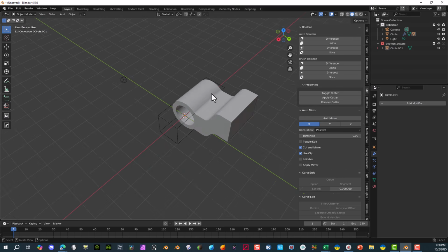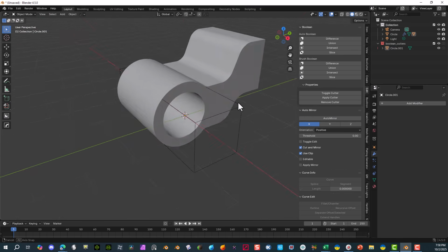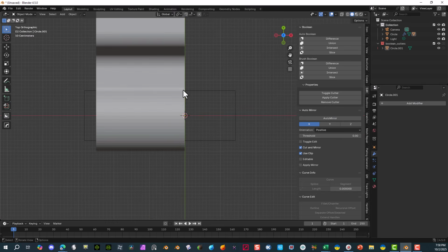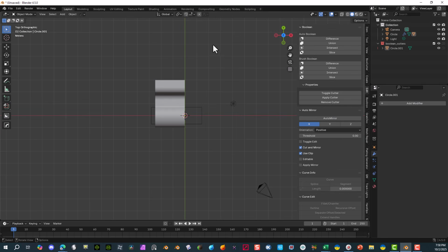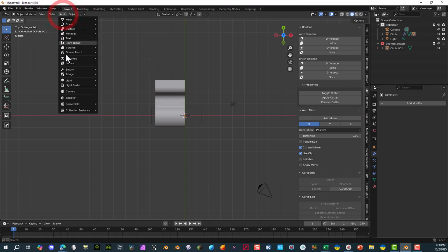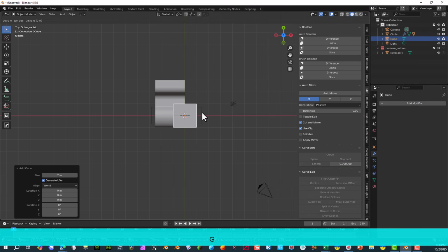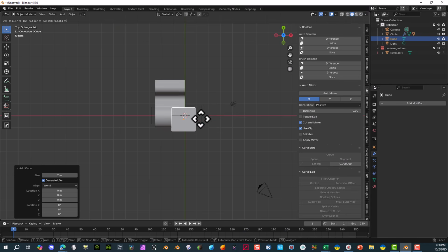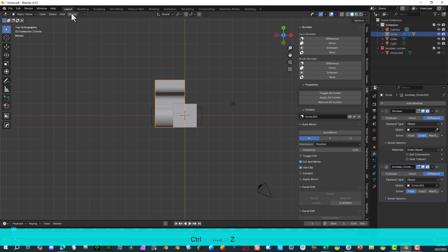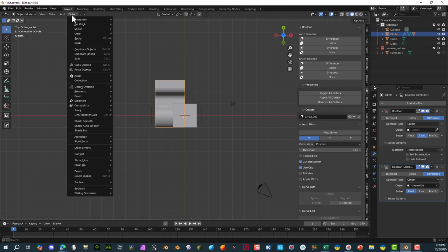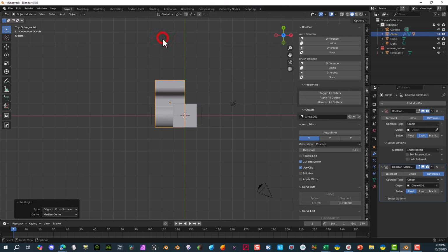I'm going to start adjusting the object itself. So I'm going to select it, and we're going to start moving this inward, basically. First of all, I'm going to get to the right angle here. So first I'm going to add in the standard cube, exactly the normal cube. And we're going to now position the other part into the space. So here we go. But the best way to do this is to go to object mode. We can go in and go to set origin. We're going to do this to the center of the mass.